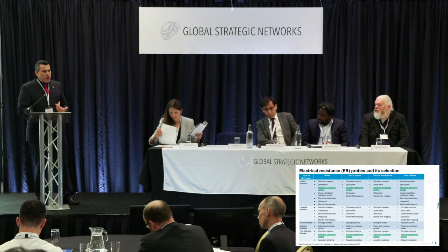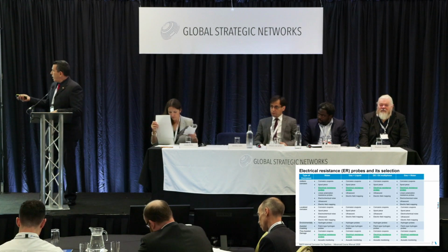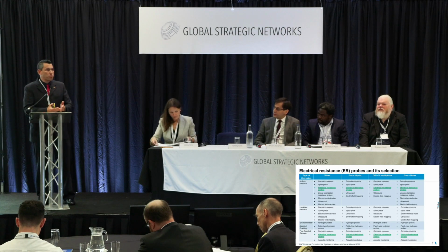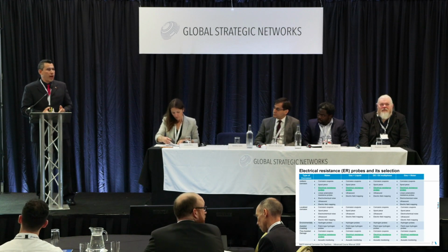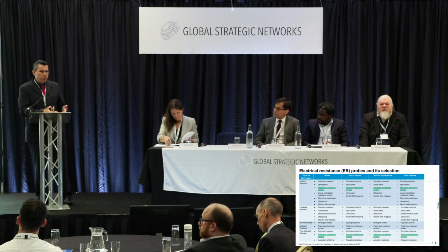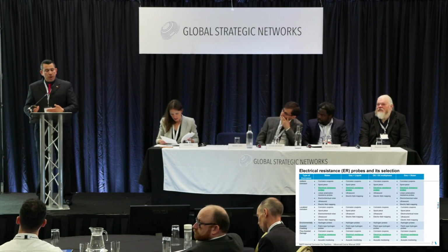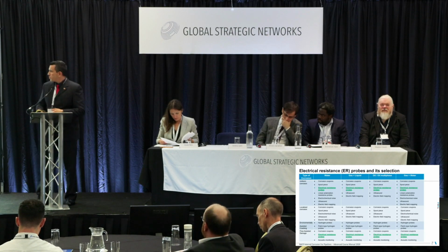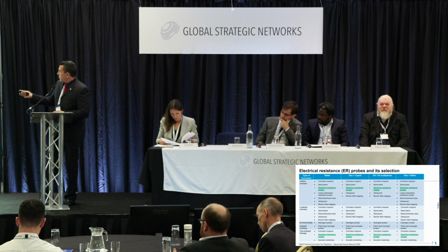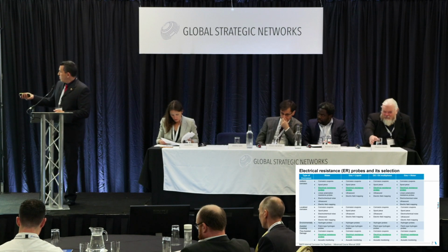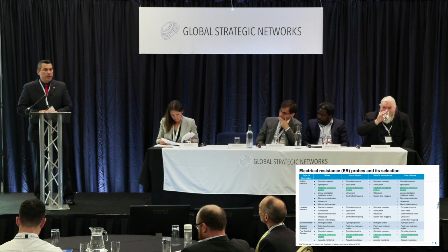Another way to think about this is, what type of media do I have? Because some of you might be operating assets that are gas producing or oil producing, or you have, as part of the production process, water, produced water. So there are tables that might help you to assess what type of process you have in your system, and the expected degradation mechanisms.